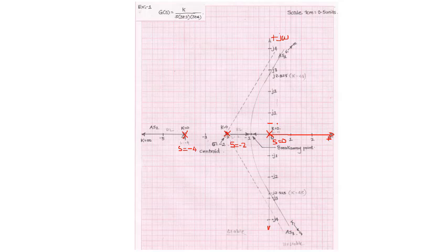Then between the poles, the root locus lines which we have highlighted, we are going to bring here. We know between S is equal to 0 and S is equal to minus 2 there is a root locus line, so we'll highlight this one. And between S is equal to minus 4 and infinity there is another root locus line. This one we are going to highlight. So here we will write RL, and here also we are going to write RL.